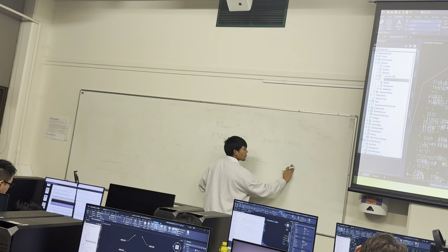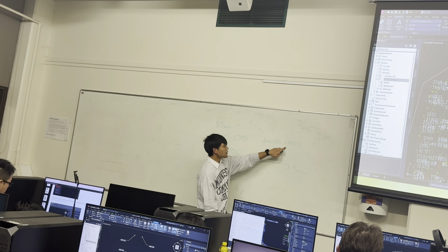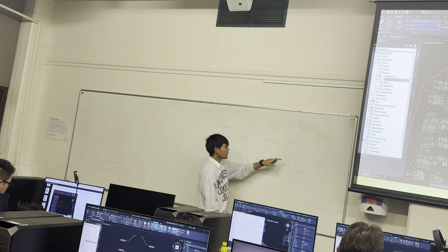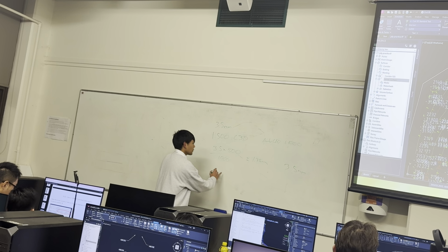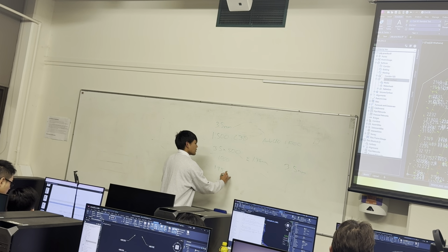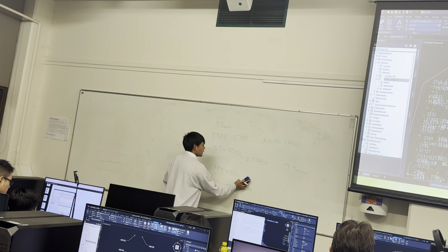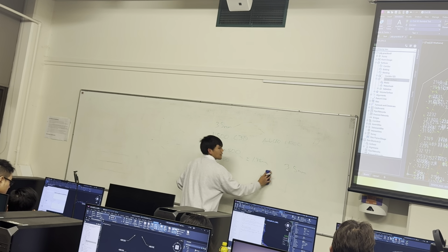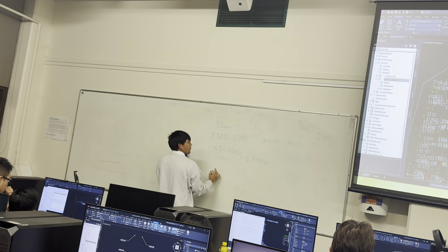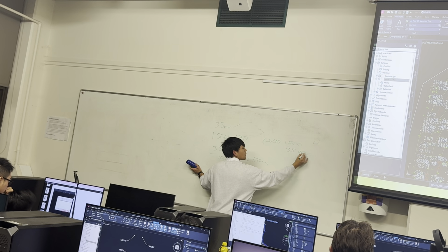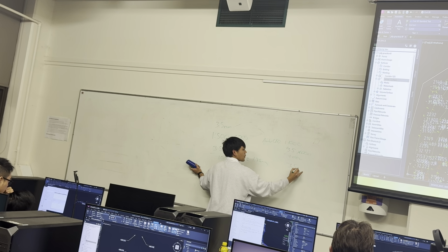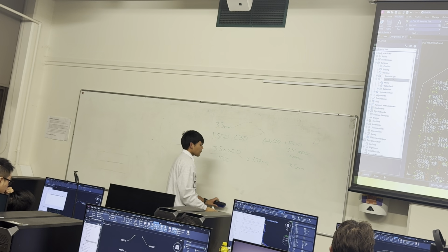Right? It will go back to 3.5 because it will ×2 that, because AutoCAD is in 1 to 1000. So what we'll do is we have this again. If we do 1.75 times 500 divided by, sorry, there's a quicker way to do this. What we can do is 3.5 times 1000 divided by 1000 plus, so we just use the same one, 3.5.